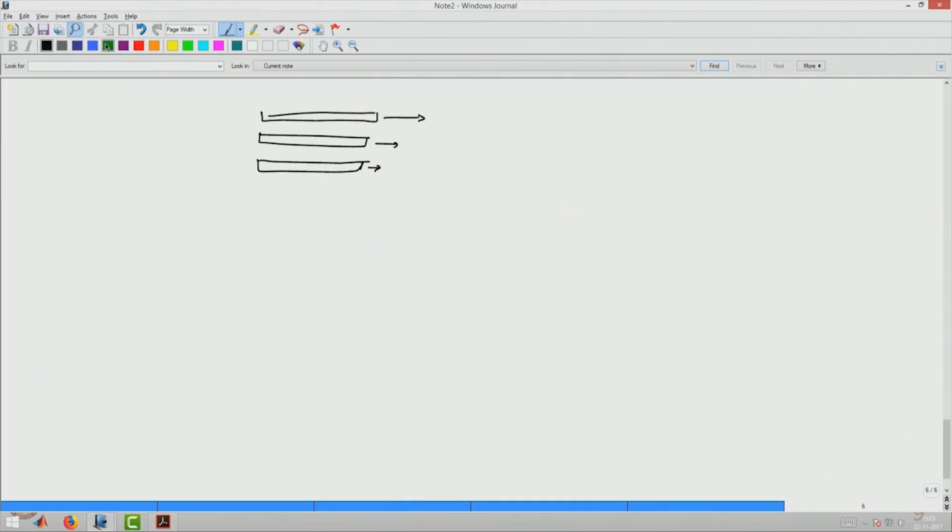All of these are balancing each other by having a set of stresses, and all of these stresses are constant. Each layer exchanges the shear stress with the other layer, and the value of the stress does not change as we travel in the y direction. This is based on the linear momentum balance for a simple shear flow in a rectangular coordinate system.